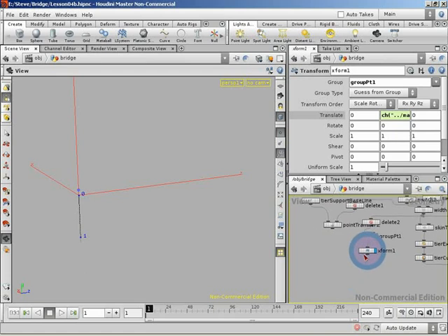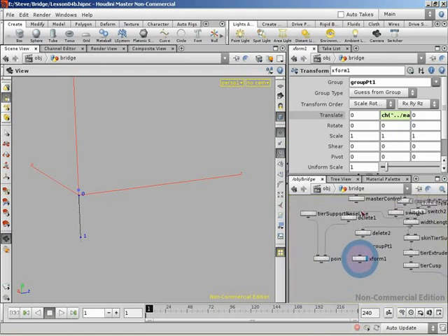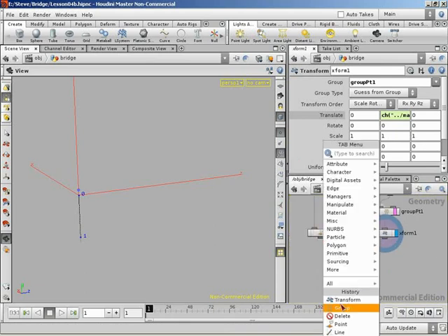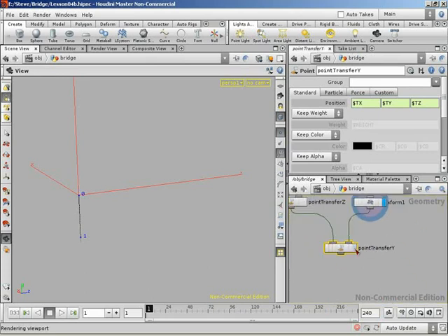So with that in place, we've transferred over our position in Z from the curve that was running in Z. So now let's do the same thing with our position in Y. So rename that guy, wire this as our second input, and if we simply come down here, I'm going to take ty, I'm going to take the negative of ty, and we're dealing with our second input, so if we append a 2 to the local variable, that's referring to the second input's local variable for that.